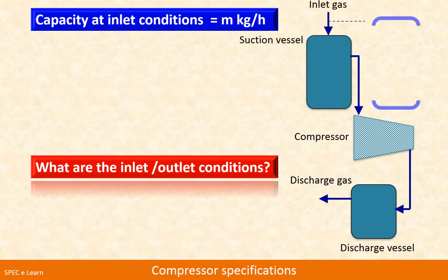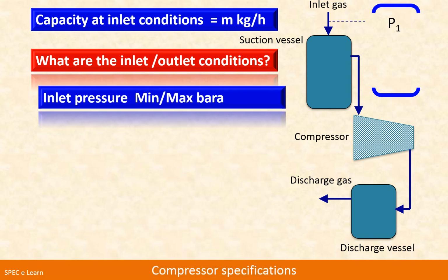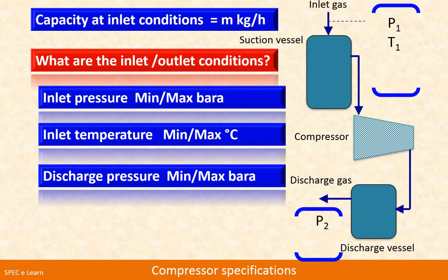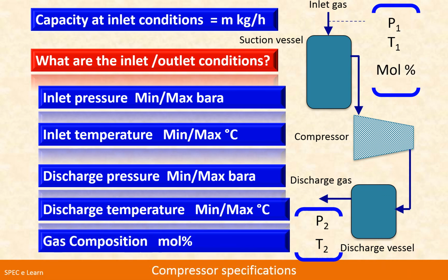Capacity at inlet conditions. What are the inlet conditions? Inlet pressure, minimum, maximum, inlet temperature, minimum, maximum, discharge pressure, minimum, maximum, discharge temperature, minimum, maximum, gas composition.